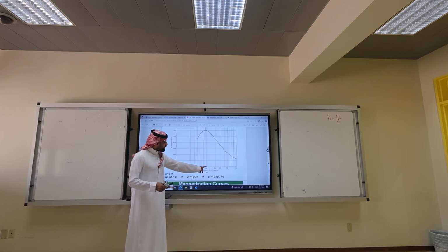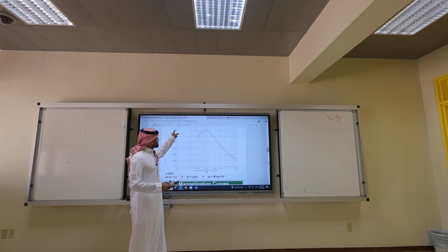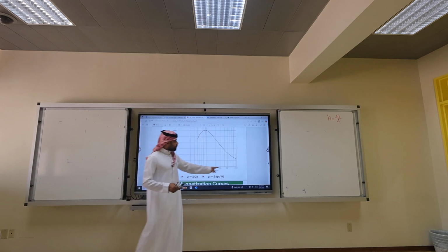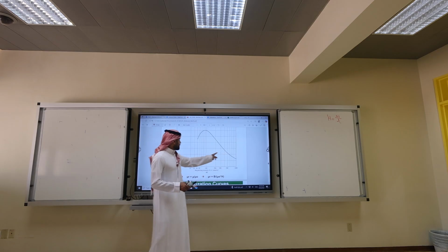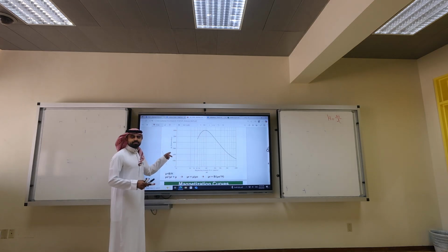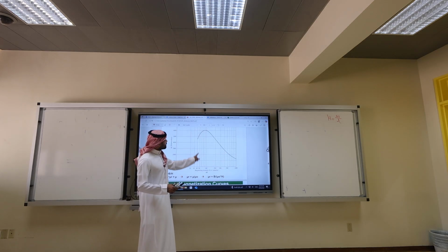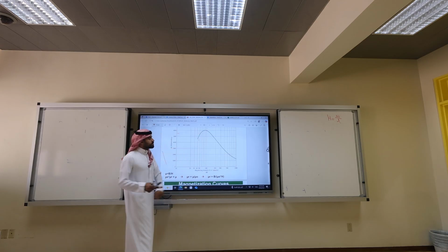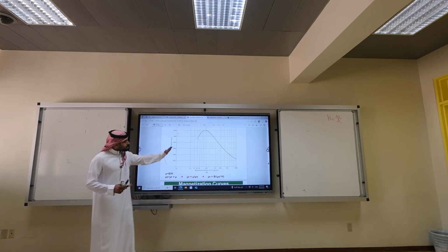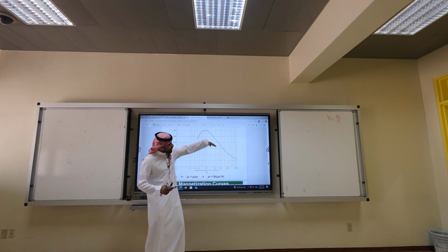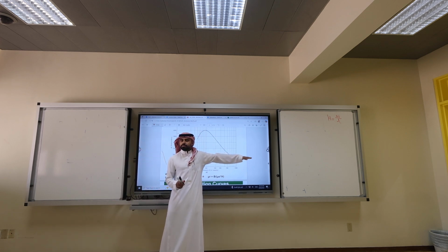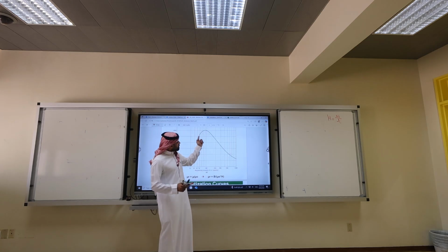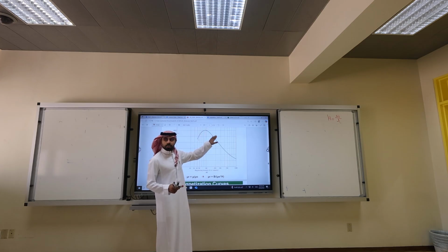For me, for 100 H, what is my permeability? 6,000. For 500, what is my permeability? 2,000. For 50, what is my permeability? 5,500. So permeability changes itself until I go to saturation. So you operate here at the knee, or maybe this is the knee. You pick your permeability, you pick your design, which mu you want to operate at.